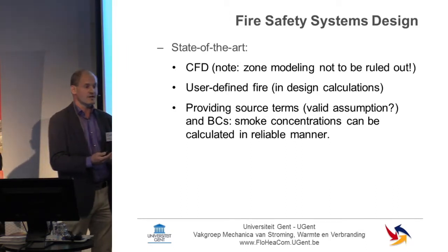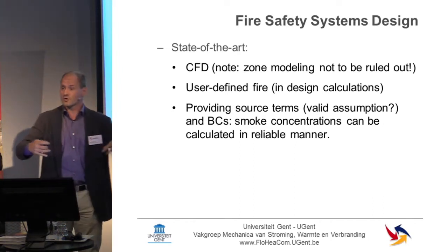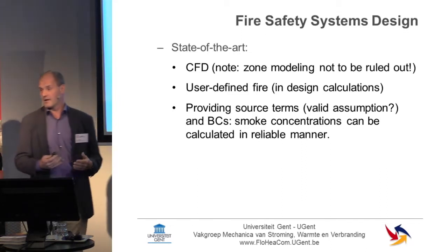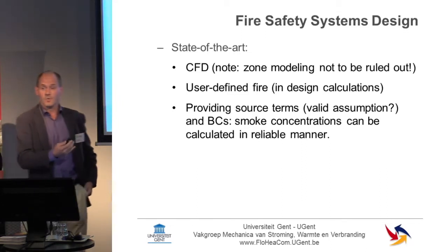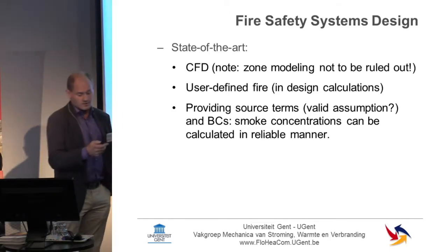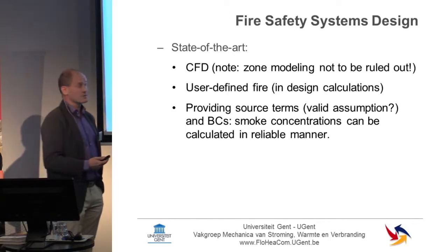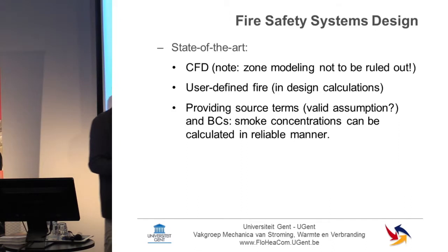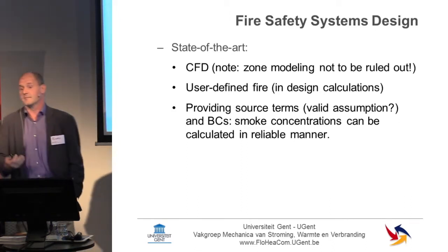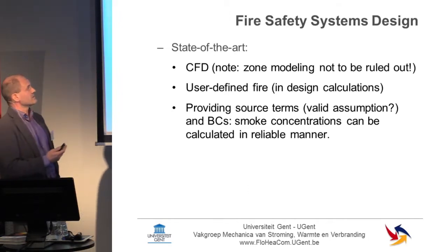A certain station you want to calculate a fire scenario with CFD, but the adjacent subway tunnels and other stations, you may want to approach them with simple zone modeling in order to make CFD possible in this one station. In any case, we have to deal with the fact that the user, in the context of fire safety system design, will have to specify the fire when starting calculations.